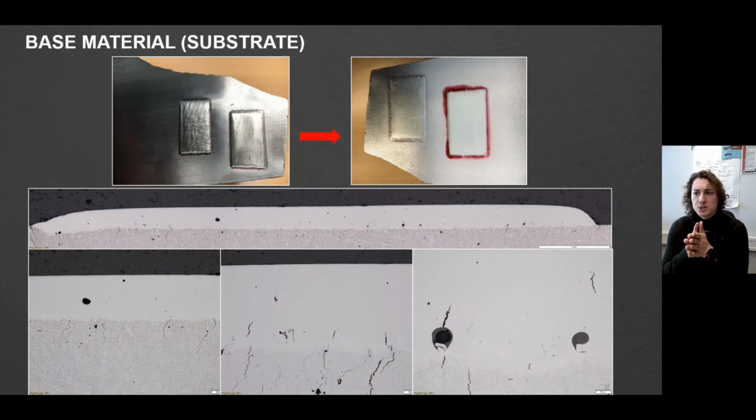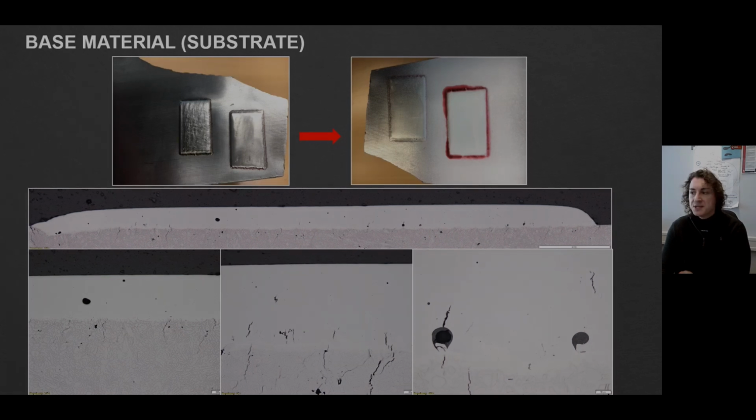Sometimes it's also important to understand that looking at your coating properties from just a visual point of view, even pre-grinding your surface and doing dye penetration tests, does not necessarily provide you a right result. So please never underestimate the influence of metallographic investigations. And here's one of the examples where you can see that having some complex cast iron substrates might lead to crack formation in the border region between a coating and substrate, even cracks propagating into the substrate. Understanding this can help you realize that your process is not always as easy as you imagine, and many defects cannot be found so easily.